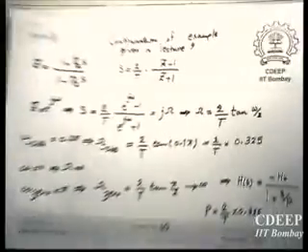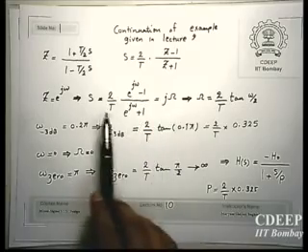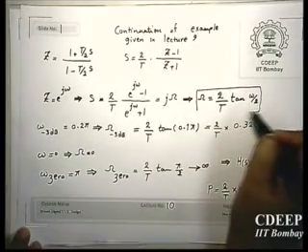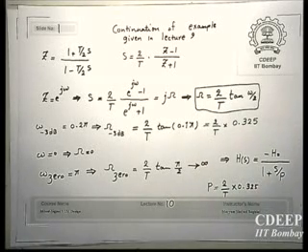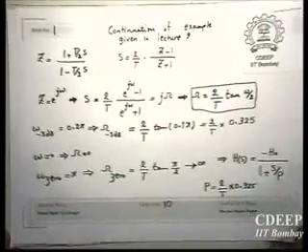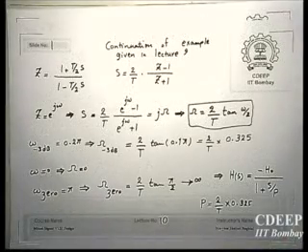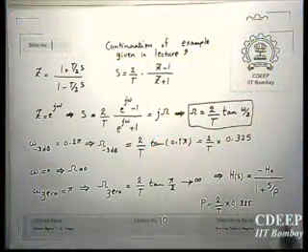And here the only information which helped us was the more detailed and accurate relation between capital omega and small omega, which is not a linear function. So this warping is done. Therefore now when we want to map it back to the digital domain or discrete time domain, we are careful that now we are using the realistic value.